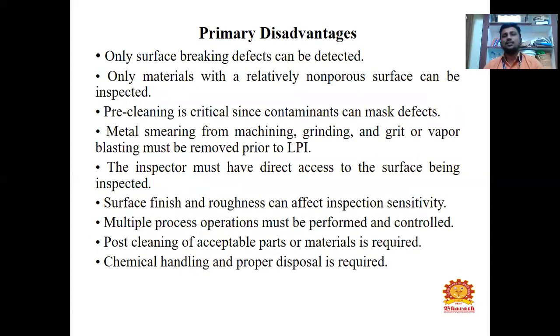Then disadvantages of the liquid penetrant method. Only surface breaking defects can be detected. Here we cannot find other defects. Only relatively non-porous surfaces can be inspected.